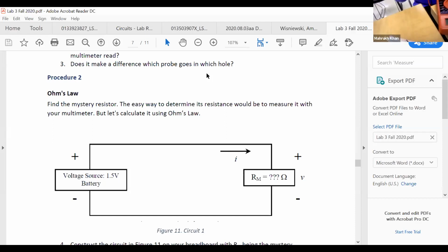First, I just want you to put the cells in it. Okay, don't connect it yet in the circuit. Just put the cells, these batteries, in it, and put it aside by the breadboard. And then I want you to put these two wires. One wire is going in the positive power rail, and the other wire is going in the negative power rail. And I want you to connect the negative one to one of the points of this resistor. Once I connect it, I will show you.